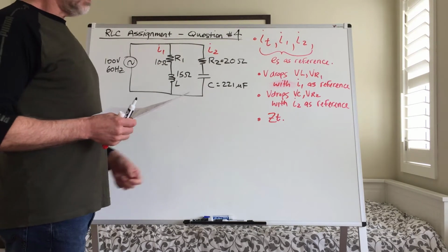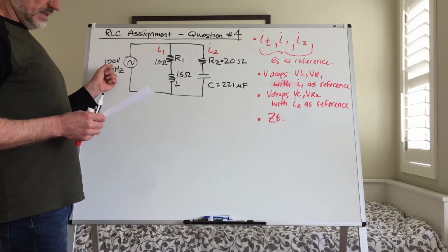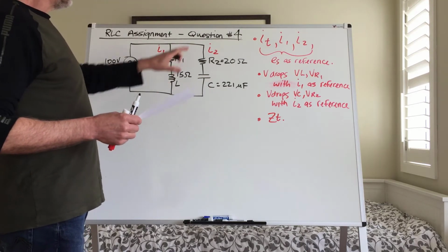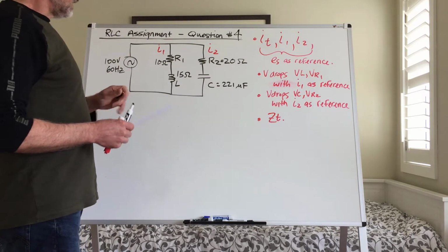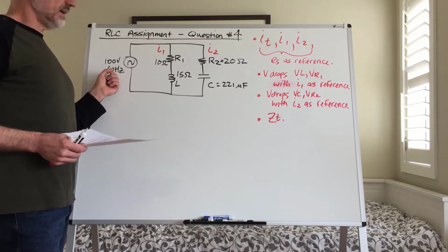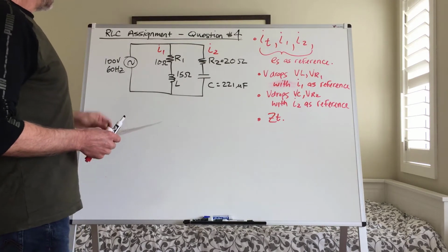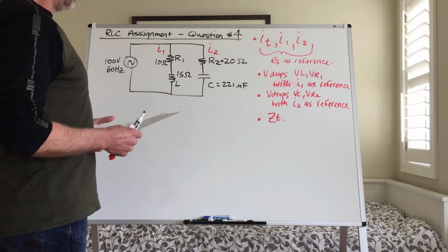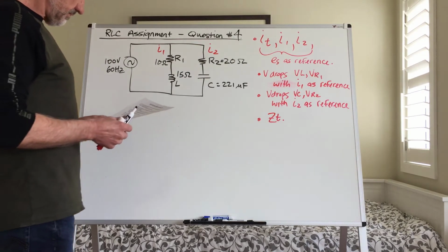So we've been given a value of capacitance there, which we'll have to use with the frequency in order to determine its reactance or its opposition. So once we start working on branch 2, we'll have to address that. Now, I just want to remind you guys once again, in any problem where you're not given the frequency, like we are here, don't forget you're to assume 60 hertz and move forward with 60 hertz. So that means if this wasn't given, you wouldn't have to ask, because you'd assume 60 hertz and an angular velocity of 377.